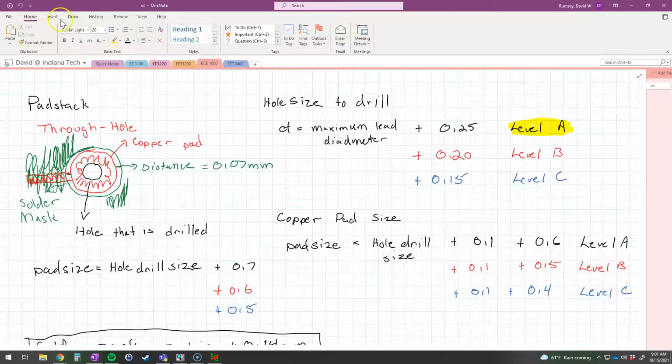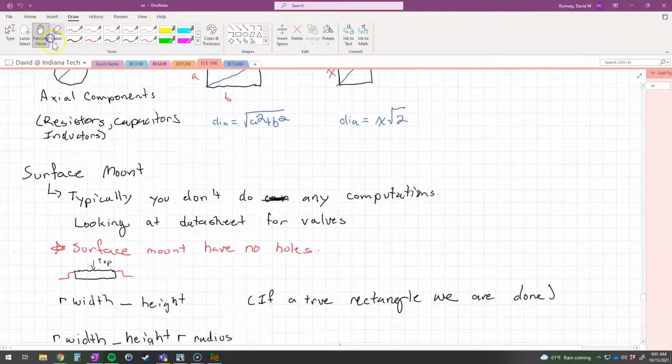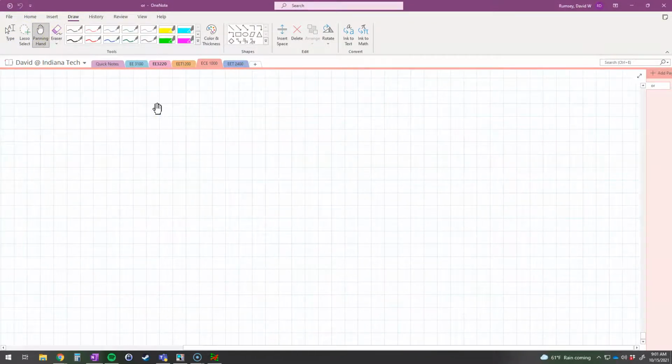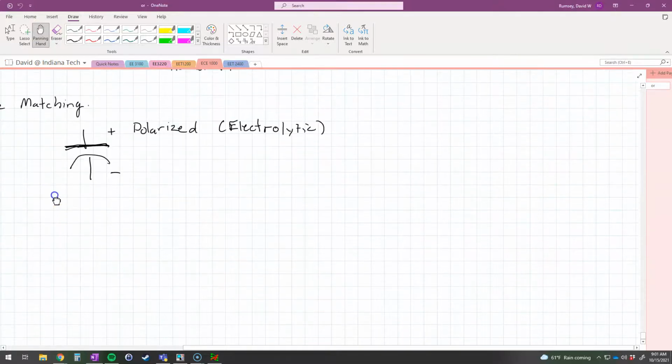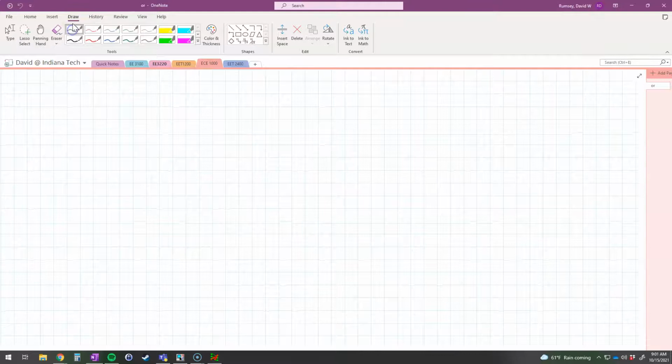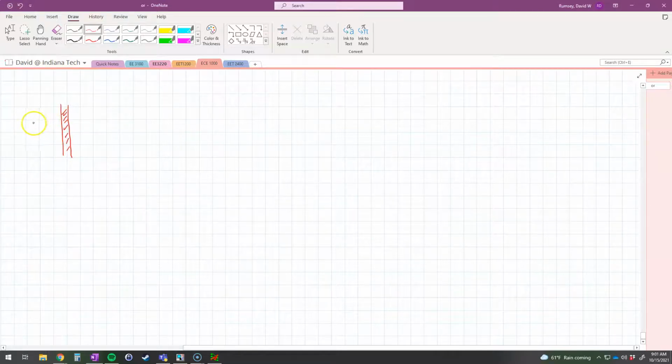So let's go here. Okay, so the line-to-line spacing is, okay, I have a trace here. And now I've said that the minimum width of this, it's not saying the widths have to be, but I'm saying the minimum width is 1 millimeter. So what we're saying is this trace here, if I was looking at the dimension here, that has to be at least 1 millimeter. It could be bigger than 1 millimeter, but it has to be at least 1 millimeter.